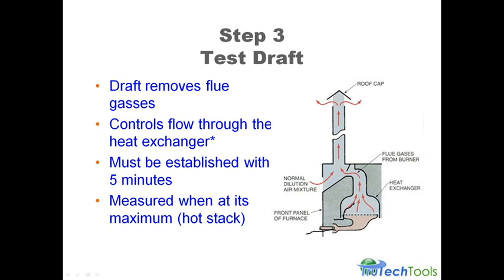And because the flue gases are naturally buoyant and hot, that warm air rises, right? That warm air rises, it's going to pull in the secondary air right behind it. So the primary air is entrained by the burner and the venturi. The secondary air is entrained by the flue gases being naturally buoyant, flowing up to the heat exchanger.